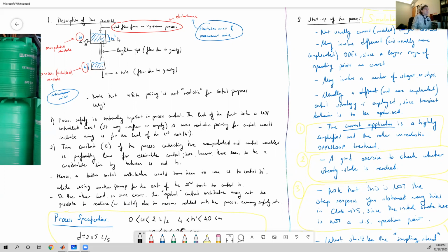Here the problematic points may be the overflow of the first and the overflow of the second tank. When you control a process like this, please note that we would not be controlling H1. The water level H1 is not controlled. We are controlling H here, but we let H prime loose.